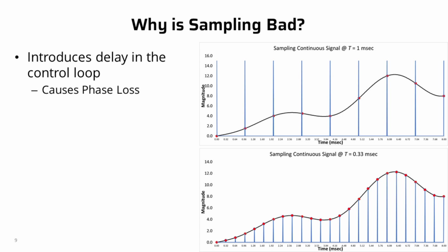And so you get that quick sample of where you're at, and then you have to make some decisions in between. Now imagine that the windshield, instead of flashing at 1 second, starts flashing at 5 seconds. That really would start feeling uncomfortable trying to stop on time. But now imagine it flashes at a kilohertz. That probably almost feels like real time to you, and you almost wouldn't be bothered by that. And so that's really the question we have here: how fast do we sample so that the control system adequately senses this continuous process so that it can control it?